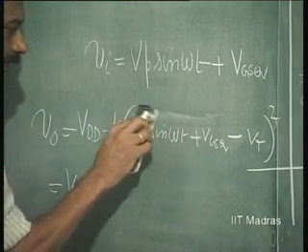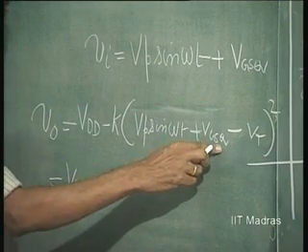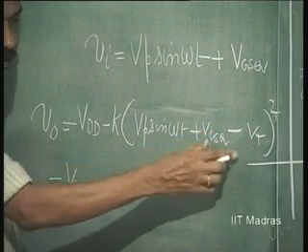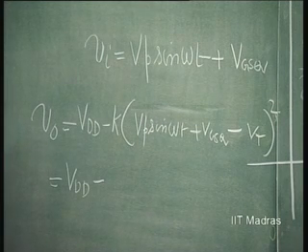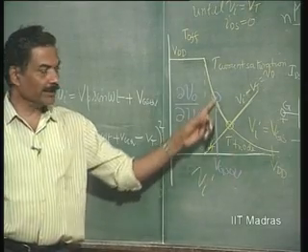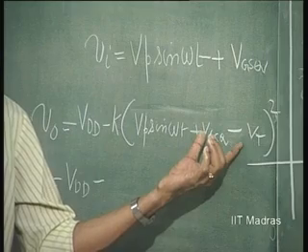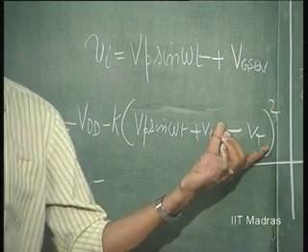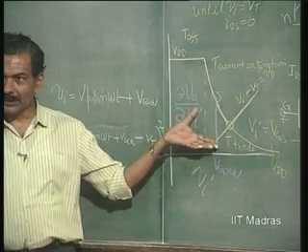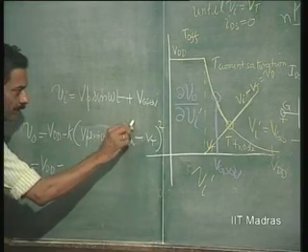This is nothing but the time varying VGS, but this is VGSQ DC minus another DC. So, VGSQ minus Vt is a DC. VGSQ has to be necessarily greater than Vt in order to locate it in the active region. So, this is a positive quantity, VGSQ minus Vt is a positive quantity for this n channel device. So, this therefore can be put as a constant.